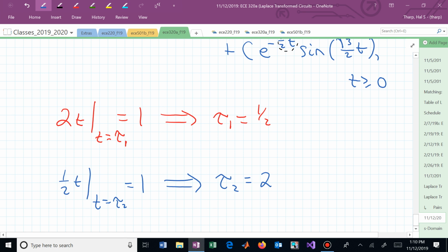And if we just agree with a shake and a nod that we'll say it's gone after 5 time constants, we're down to 1% of where we started after 5 time constants. That's when we assume we're at infinity. Kind of like to joke, let's go to infinity and beyond. It doesn't take very long in electrical and computer engineering to go to infinity. 5 tau,